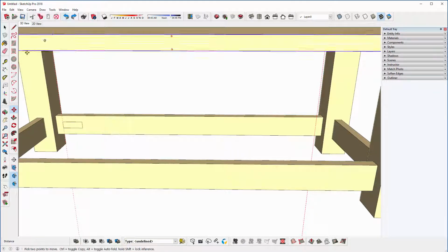So we'll go undo. So select tool again, click on the railing, get the move tool, press Control before you start, and this time I'm going to copy it from the bottom right corner. Click to begin, take it far right until it hits the guideline, click, and this time we're going to divide rather than multiply. So just after copying, just after you click, you can type in 11 / enter, and it will automatically divide it up into 11 times.